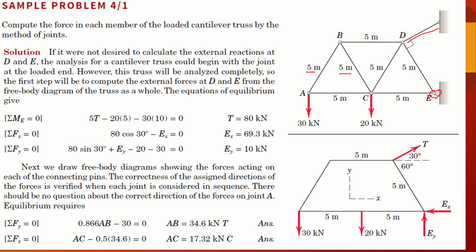The easiest way is to start with joint E. With the help of the forces acting at joint, taking moment about joint E, we will be able to calculate the value of T. So, assuming the sum of moment about joint E is equal to 0, we know the tension T is at 90 degrees from the arm DE.